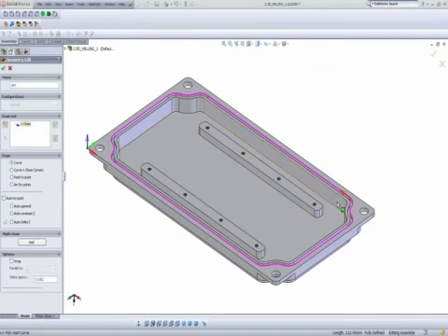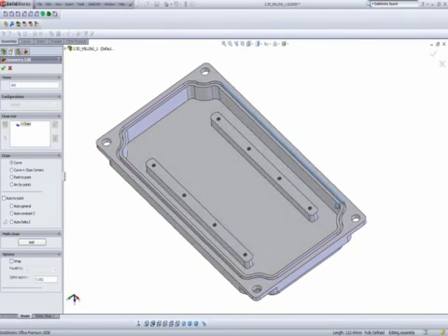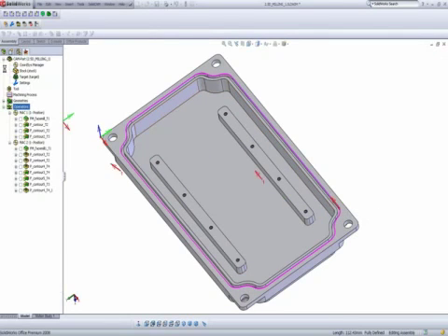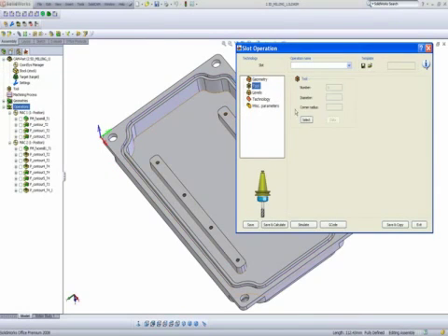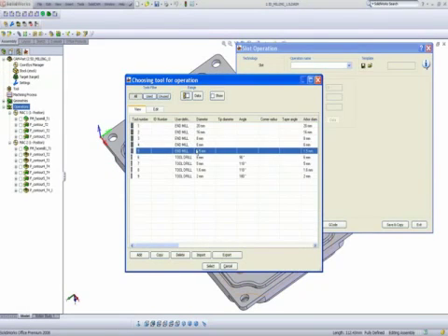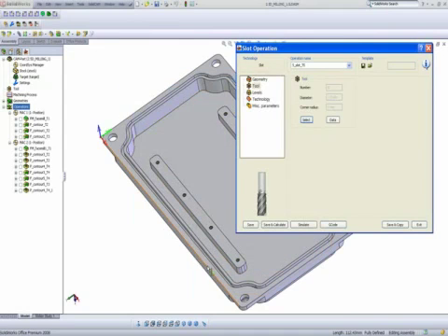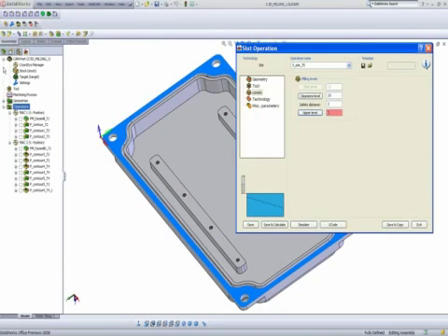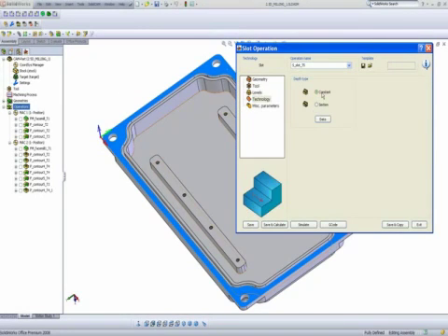Now you'll note with the position of the arrow that I would want to work on the left hand side of this particular slot. Now I will choose a tool. Like I said, I'll be using a tool that is 1.5 millimeters. My levels, my upper level will be over here. And when I go into my technology area, we have what they call constant, which is exactly what I want to do here, or section, if I want to work on a specific section cut.